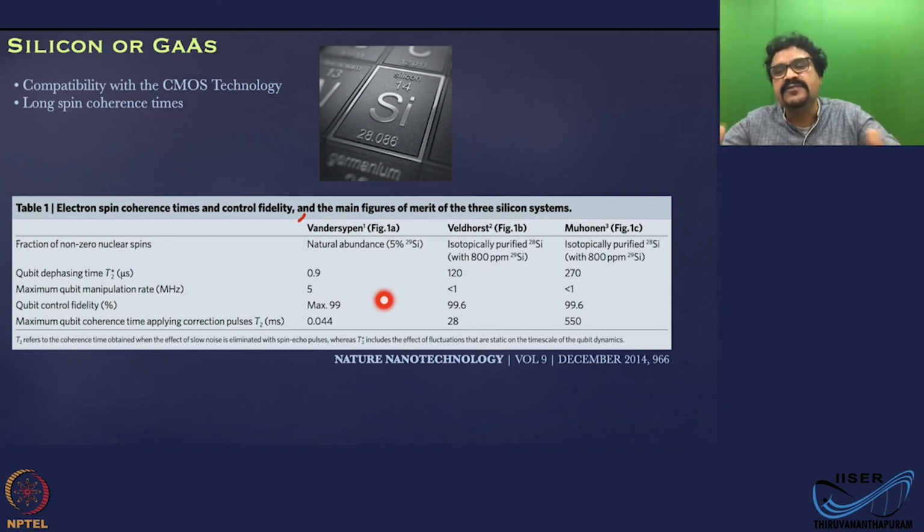the electron spins. That is exactly where silicon as a wonder material steps in. For silicon 28, it's a natural isotope, which is 94 to 95%. I don't remember the exact number, but more than 90, close to 95% of natural silicon is silicon 28, and the rest, a few percent, is silicon 29, which has nuclear spin. So you have natural silicon that is close to 5% silicon 29, and isotopically purified silicon, which is almost silicon 28 with a few parts per million.